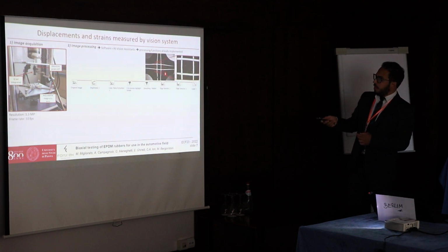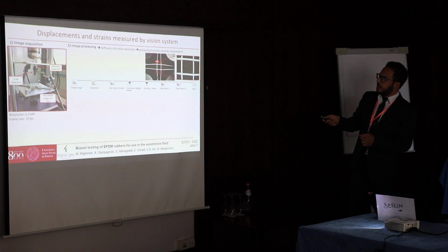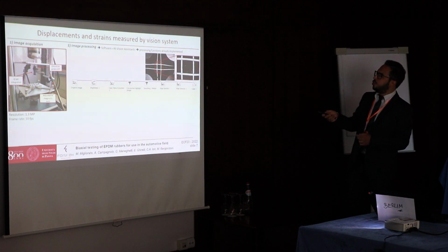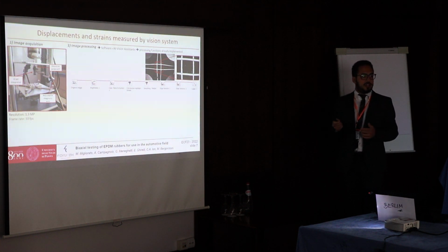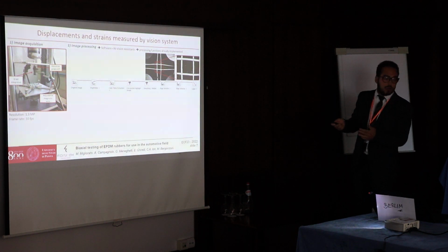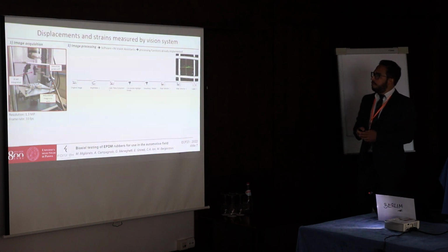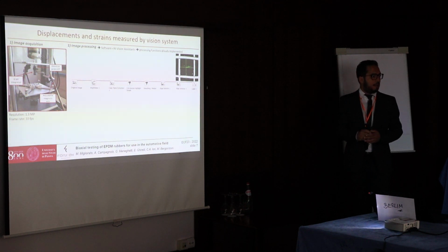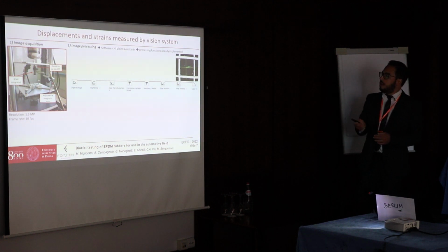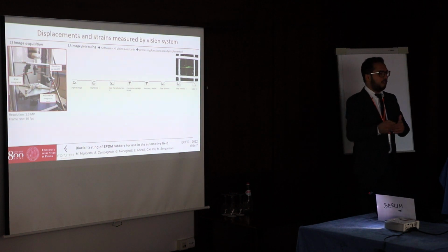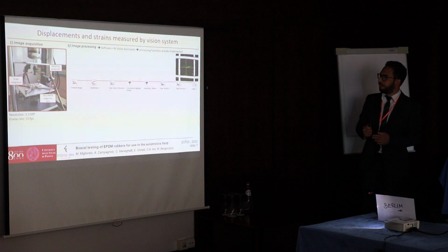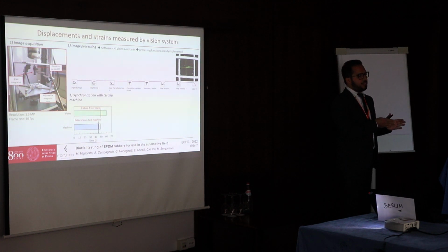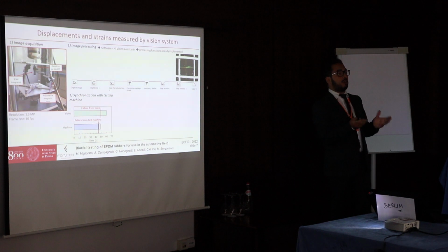Then the edge pixels of the markers have been detected along the two orthogonal loading directions on the basis of the difference of brightness of the markers as compared to the background. Then, given the coordinates of the markers followed throughout the test, the National Instruments Vision Assistant also provides the displacement of the markers with respect to the reference condition. However, the testing machine and the vision system were not synchronized.